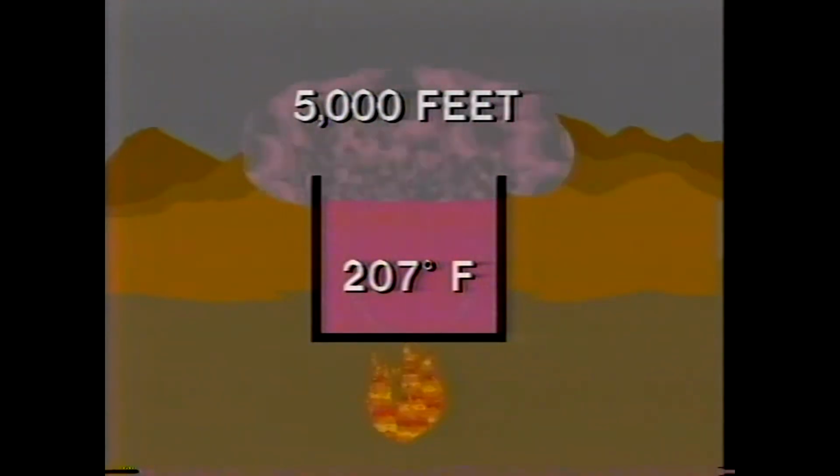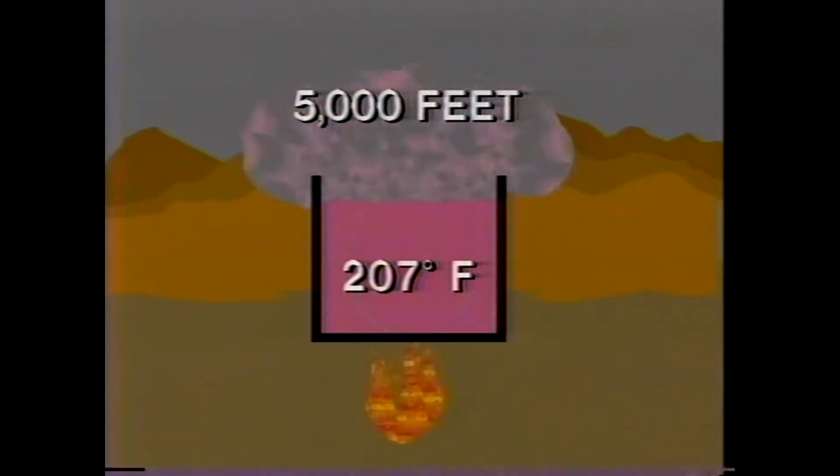With this basic process in mind, let's look at the way pressure affects temperature and temperature affects pressure. Again, we'll use the example of water to demonstrate this. As you know, water boils at 212 degrees Fahrenheit at sea level. The boiling point is lower if air pressure is lower, such as at high altitudes. In Denver, for example, which is above 5,000 feet, the boiling point of water is about 207 degrees Fahrenheit. By the same token, increasing the air pressure raises the boiling point.